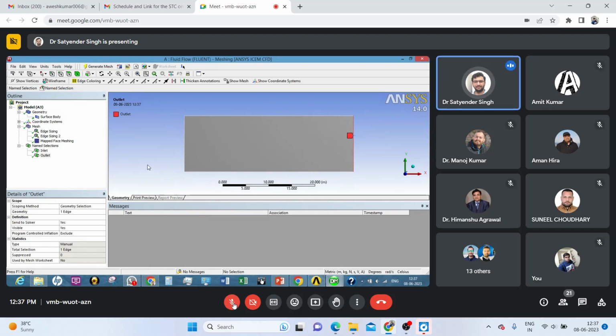Okay, fine. But as far as the problem is concerned, for a duct flow or a pipe flow or flow through a rectangular or any other shape, because of the no slip boundary condition, or from physical relevance viewpoint, because of the shear present at the wall, a boundary layer will start forming, which is symmetric on both of the top and bottom faces. So we need to create a very fine mesh near the wall. For that you can go for biasing also. So there biasing is available. Biasing type, you can select a particular biasing type. So I'm not going to give you the details of that.